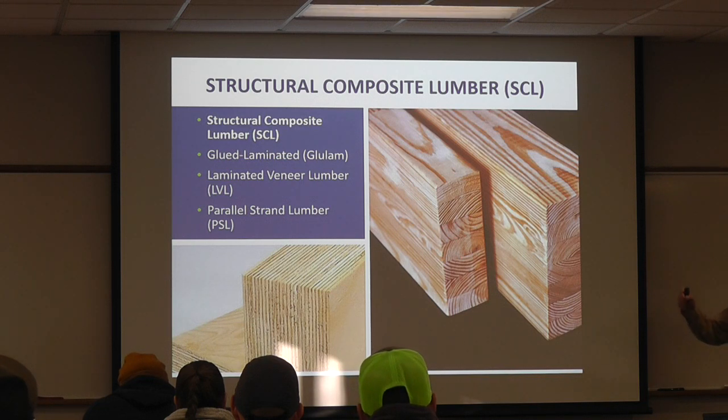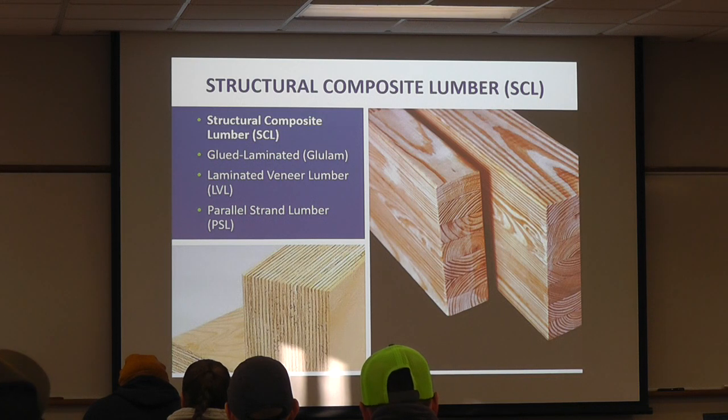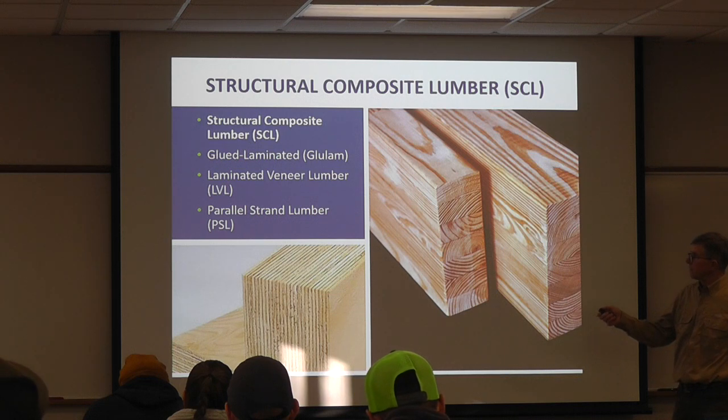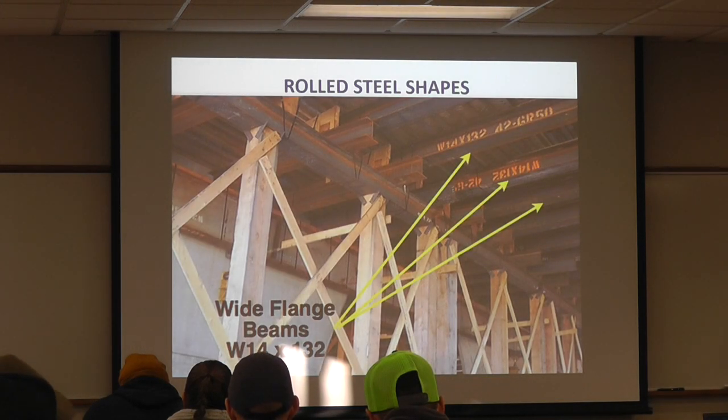So instead of just taking a tree and making a 3-inch by 12-inch piece, they take a bunch of smaller pieces, glue them together, and make the larger element. The same thing with some of the ply forms that are put together. So those can be used. They're certainly fine. The LVL people have whole strength tables that show the strength of their material.